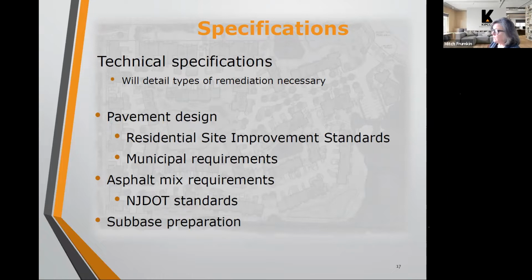In some cases, the wheel of the truck actually goes through the soft spot and makes a rut in the base course. Those are areas that will need full depth repair, where they will dig down not only through the base layer but into the subbase layers. And if they cannot achieve bearing capacity, they'll put down a geotextile fabric, backfill, and then build the full depth pavement on top of that.